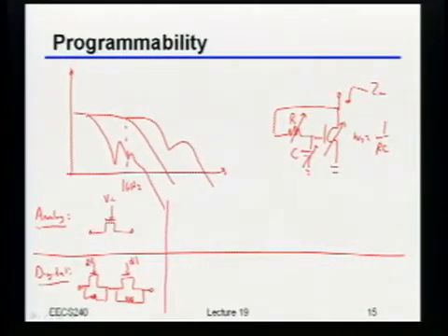Okay, how about for changing the capacitor? Let's maybe start with the digital one because that's a little bit easier. How could you do that? When you say switch cap, what does that mean? Switches to add capacitance in. Yeah, okay, so basically, I could put a switch in series with a cap, then tie a bunch of these caps up in parallel, right? So again, D0, D1, and so on. The more of those switches I turn on, the more of the caps will be connected to the output.